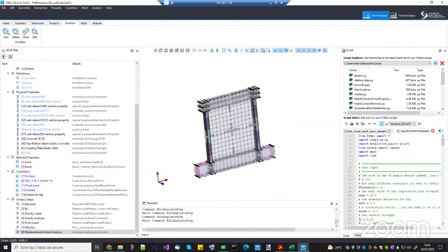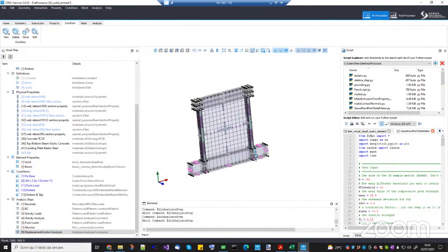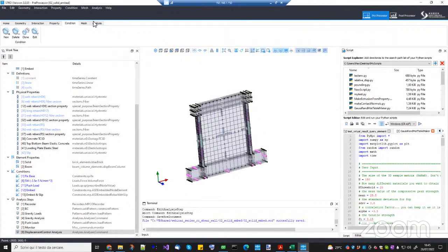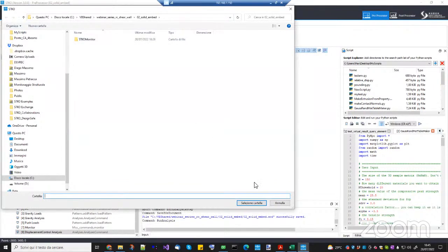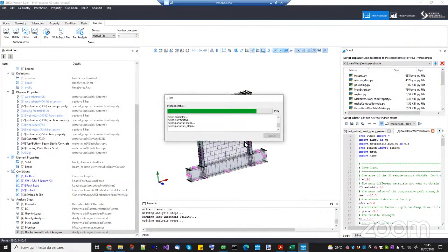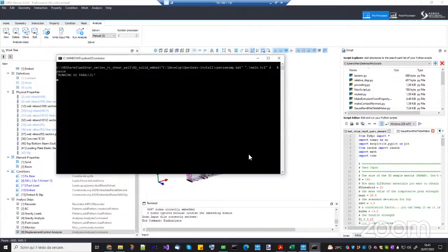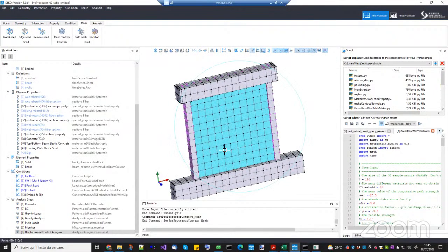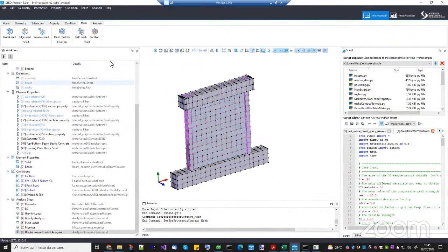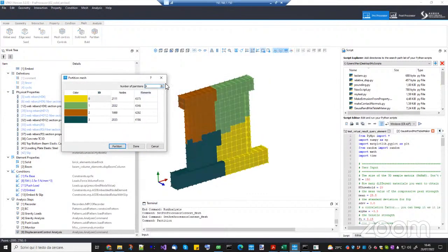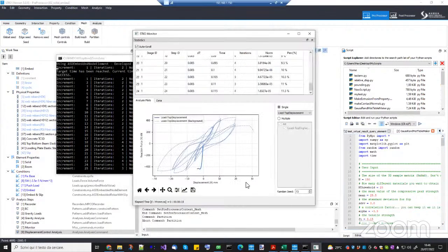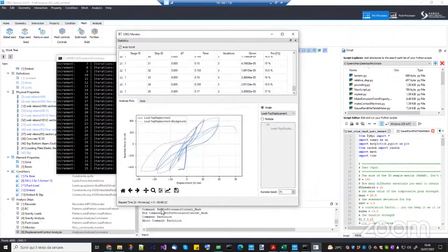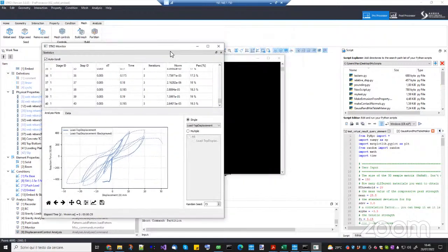Okay, so I can run this. I think it will take a few minutes. So let's see how it goes. Let's run it. I'm using, I think, 4 processors. I will show you the mesh now. So this one is the mesh. It is a quite coarse mesh because I don't have time to run a finer mesh in real time. But this is sufficient to obtain some decent result now. I'm using only 4 processors. So 15% in 20 seconds is pretty good.